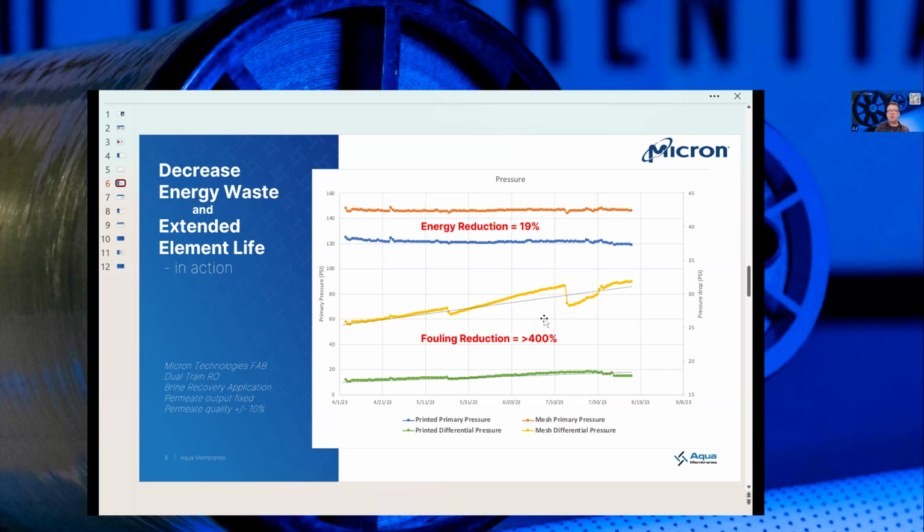Sometimes when things are hit with a hydraulic kind of water hammer, there's a force that, especially with a mesh netting, can end up displacing certain portions of the feed spacer net. After that shift has happened, there's a reduction in the pressure drop because there are spots that are more open.